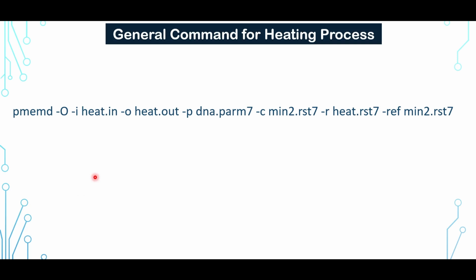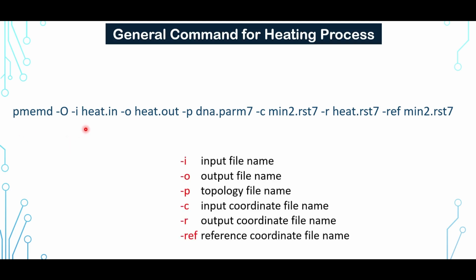This is the general command to run the heating process. So we'll use pmemd module of Amber to run the process, and this is the input file that I showed earlier, and this will be the output file that will be created after the heating process.